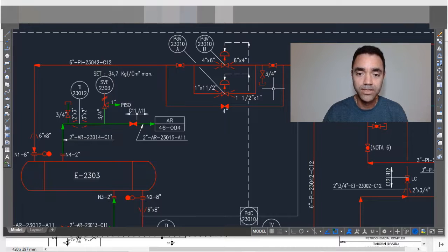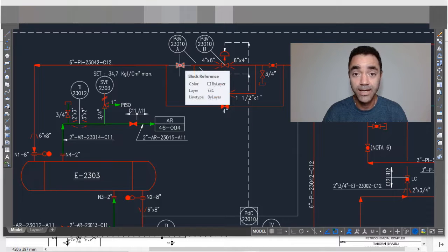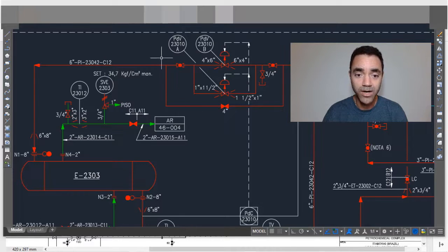And what is interesting, most often what we have for control valves is an isolation valve at the inlet, another isolation valve at the outlet, and a bypass valve, so that in a case of maintenance or replacement of any one of the control valves, the operations can close the segment, drain it, remove the fluid that will be trapped here, and operate the plant at the bypass.